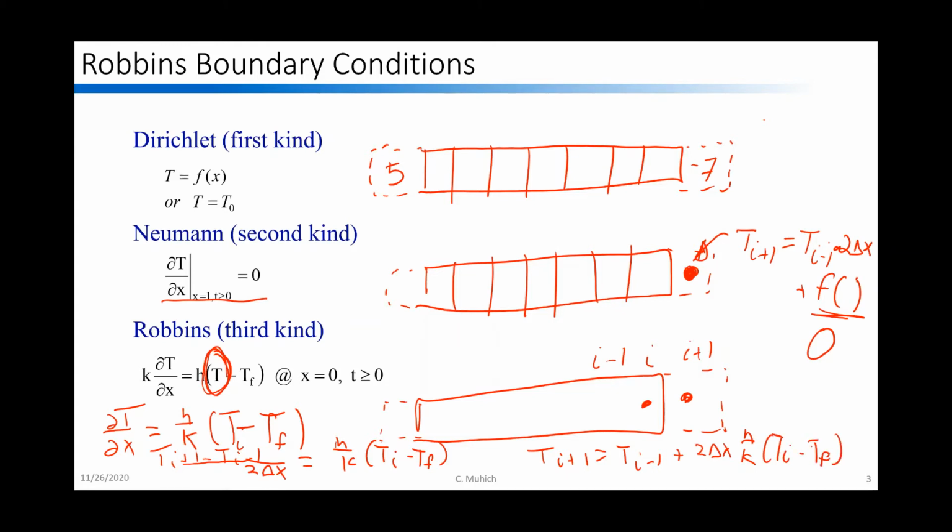Okay. So we're just adding that extra complication, but it's the same idea as the Neumann boundary condition. Instead of having this much simpler form, we have to take into account T_i in there, and we can't just say the value here is there. We may have to add an additional imaginary node into our system to take this into account, but the ideas are going to be identical. These are all of the boundary conditions that we're going to discuss for this class.